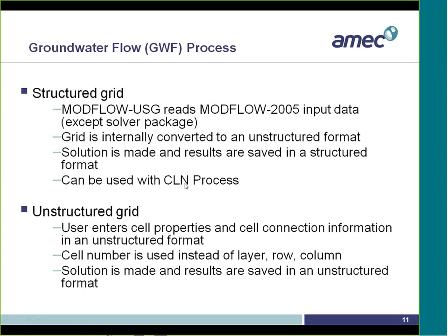You can use structured grid with the CLN process. So you can have this connected linear network. So these linear cells could be used as wells. So currently, since the MNW package is not supported, these linear cells can represent wells similar to the MNW package. However, right now it is fully implicitly coupled with the groundwater flow process and solved simultaneously.